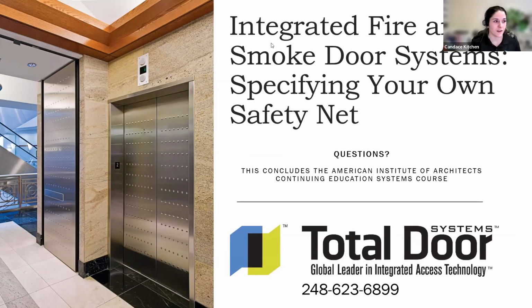While you guys are putting those in, I'll go through a question I've got previously that I thought was quite interesting. Somebody had asked me, why is a fire smoke door typically rated for 3/4 of the surrounding wall? And I think sometimes I get so blinded, I'm like, it just is. So we looked into it, and it's typically rated for 3/4 of the surrounding wall because the walls are going to have things like garbage cans, shelves, picture frames, whatever it may be on it, whereas a swing door itself shouldn't have anything in front of it, and that's why it's typically rated for 3/4.